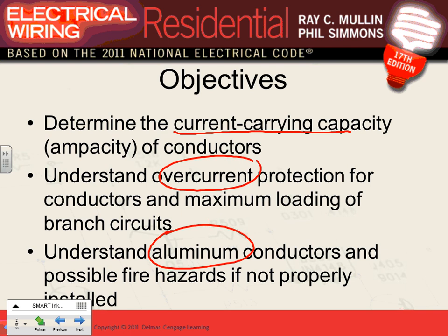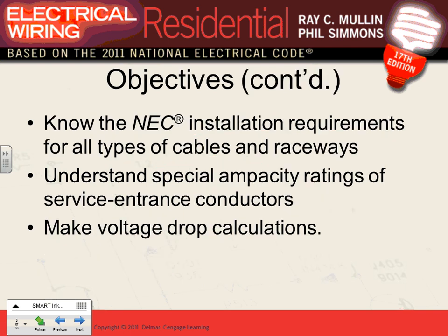Anybody know why? Because they expand and contract at different levels or values. So when they expand and contract at different values, what's going to happen to the lugs over time? They're going to loosen. What happens if you have a loosened lug at a 400 amp lug? If you have a current coming 400 amp, loosen, you're going to arc. What does arc do? Big ball of fire inside your switchgear. So bad day for a lot of people.